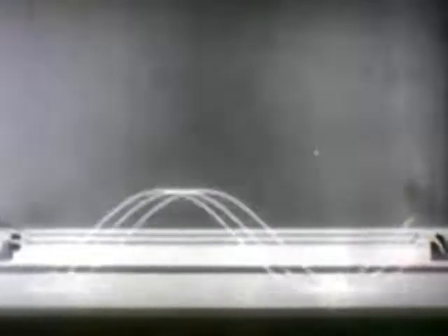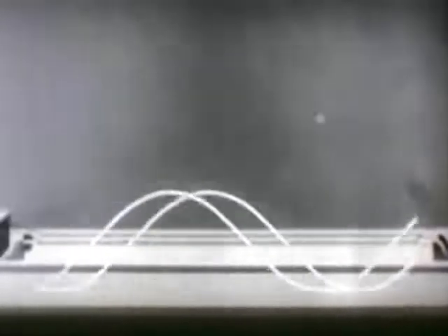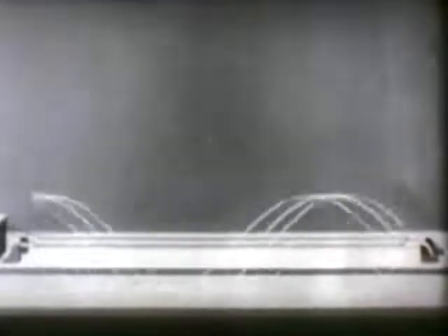Using this table model of a closed-end transmission line, let's imagine the incident and reflected waves are visible, in slow motion, of course. In this closed line, the incident and reflected waves are of equal amplitude. Now here's another phenomenon of resonant transmission lines. When an ordinary fluorescent lamp is placed near the line, it can be used as a voltage indicator. When the tube glows the brightest, it indicates a point of peak voltage in the line.